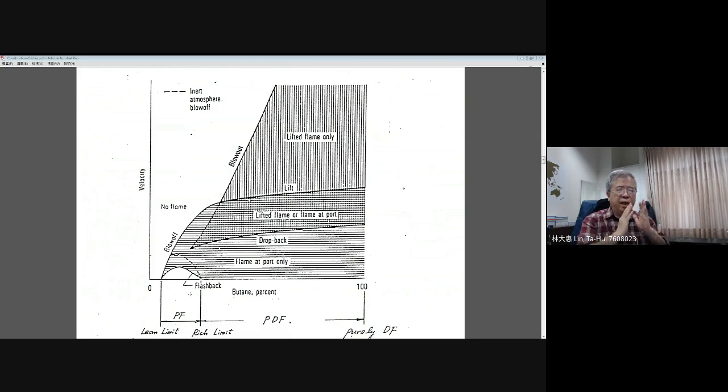Okay, and as I explained earlier, when you have a diffusion flame downstream of your rich premixed flame, in double flame structures, that diffusion flame will burn out the excess fuel on the downstream side. And this diffusion flame actually gives some support, because it creates a hot temperature region.